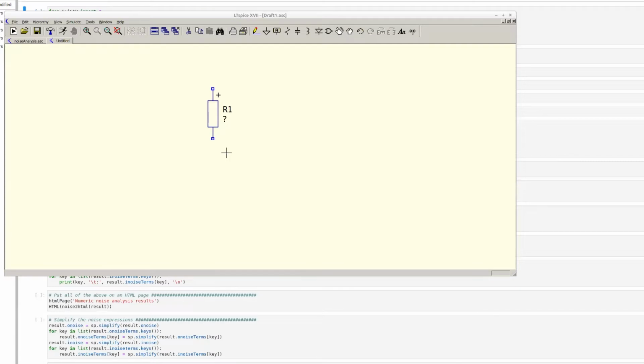So we are not going to put noise and dynamic behavior and whatever, everything together in one model, because that would result in such complex expressions that we cannot draw design conclusions. We will teach you in this course how to design things orthogonally. So first design, for example, the noise, and then design the dynamic performance of an amplifier. While designing the noise performance of an amplifier, we will just assume that the dynamic performance is okay, that we are in the frequency range of interest, we have exactly that transfer that we want.